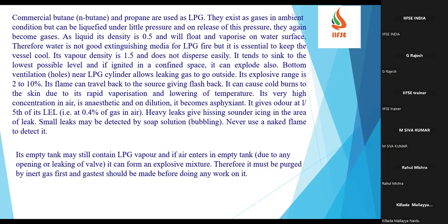And never use any naked flame for leak detection. We have to use a soaping solution to find the leak. An empty tank may still contain LPG vapors, and if air enters the empty tank due to any opening or leaking of the valves, it can become an explosive mixture.